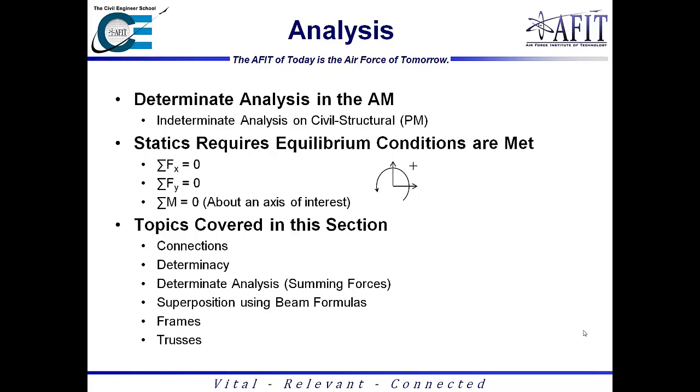So for the analysis topic of the structural portion, only determinate analysis is necessary. All the indeterminate analysis that you may have learned in your undergrad will only be included on the civil structural PM exam. But for determinate analysis, essentially everything can be solved with three equations: the sum of the forces in the x, the y, and the sum of the moments all equal 0. Those are the three equations with three unknowns, and that's determinate analysis.